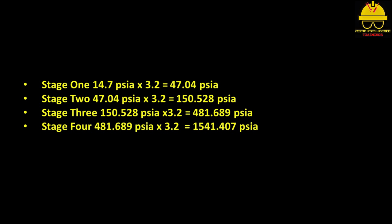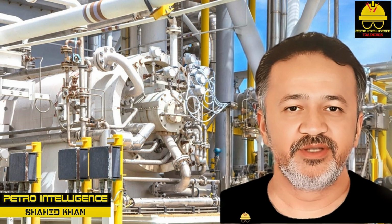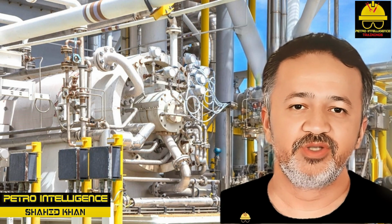The simple calculation used to calculate the pressure increase on each stage is: Stage 1, 14.7 psia × 3.2 is equal to 47.04 psia. Stage 2, 47.04 psia × 3.2 is equal to 150.528 psia. Stage 3, 150.528 psia × 3.2 is equal to 481.689 psia. Stage 4, 481.689 psia × 3.2 is equal to 1541.407 psia. The basic components of a centrifugal compressor are shown in picture.